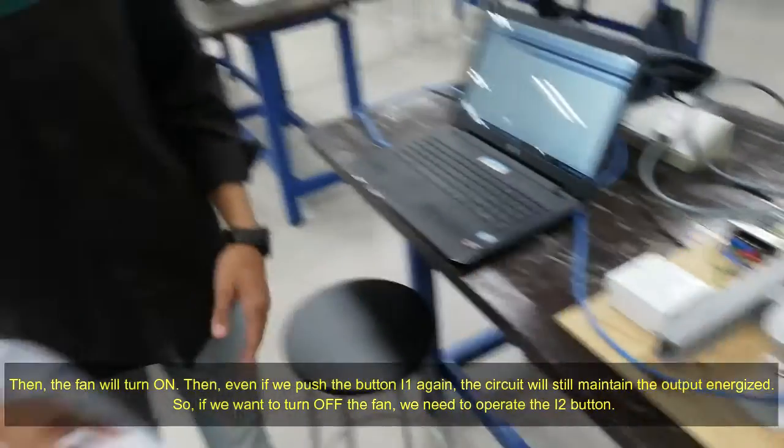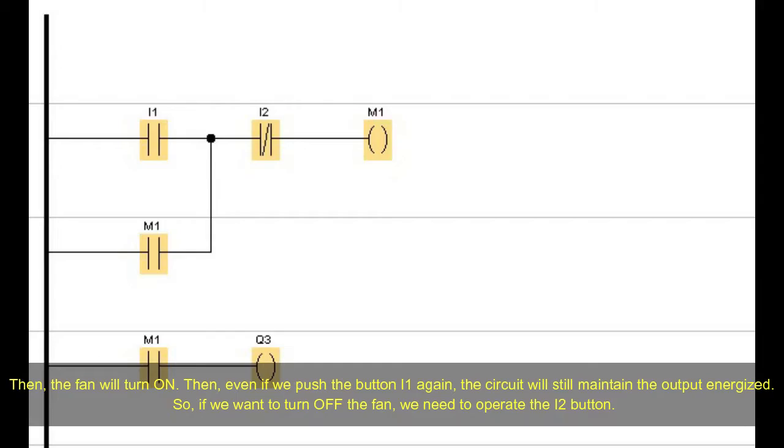Then the fan will turn on. Even if we push the button I1 again, the circuit will maintain the output energized. If we want to turn off the fan, we need to operate the I2 button.